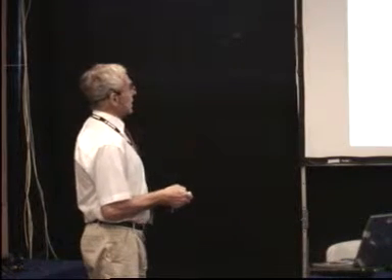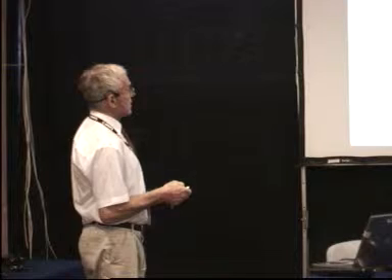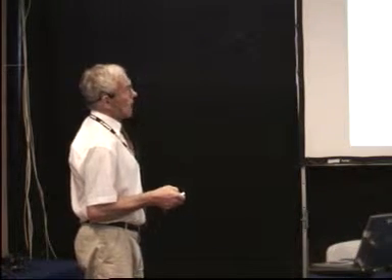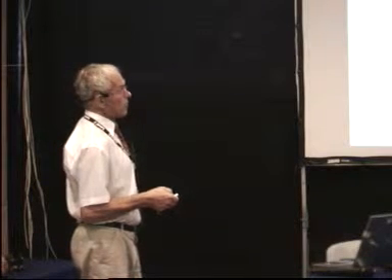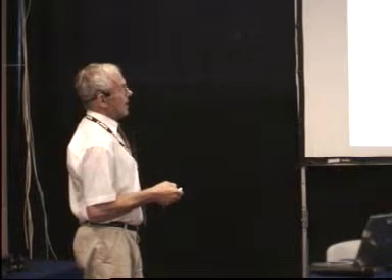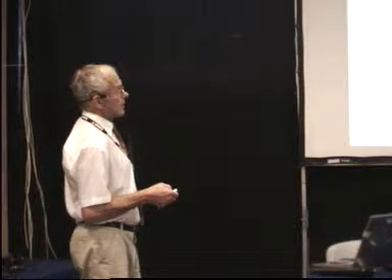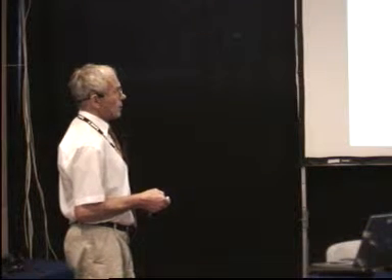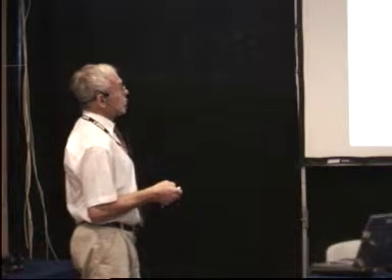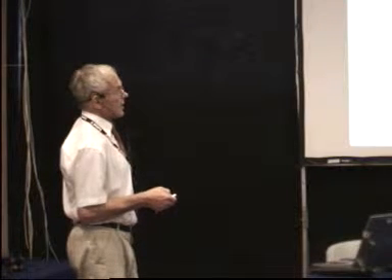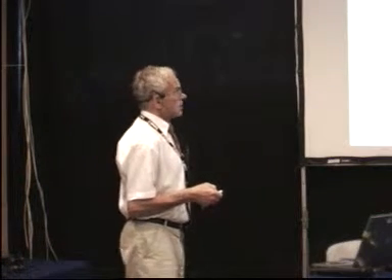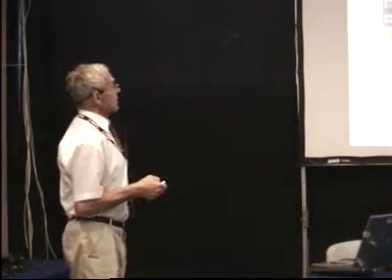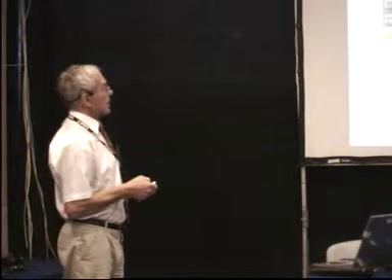Another advantage is that all these channels and all these idlers are fixed to ITU grid frequencies, to ITU grid wavelengths. If the pumps are, as I mentioned already, 10 gigahertz apart, and if the signal is fixed to the ITU frequency grid, then all these newly generated signals and newly generated idlers also are fixed on ITU frequencies. And here are the eye diagrams recorded by this sampling oscilloscope.